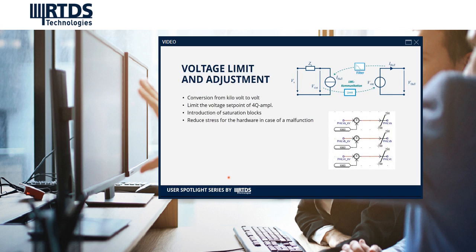Furthermore, the voltage has to be limited and adjusted. First, a conversion from kilovolt to volt is necessary by dividing the signal by 1000, because RSCAD is calculating with kilovolt and the three-phase system wants volt as an input signal.